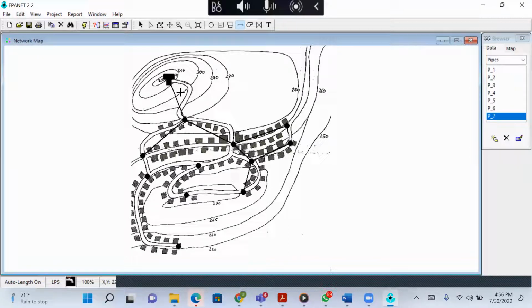So here, this is not following the street well. So I'll click this black arrow. I'll click on what we call vertex, this one. If I click on vertex, I'll come here, click on this pipe, right click, and say add vertex. The first time it will be as if nothing happened. The second time, it will add a node.